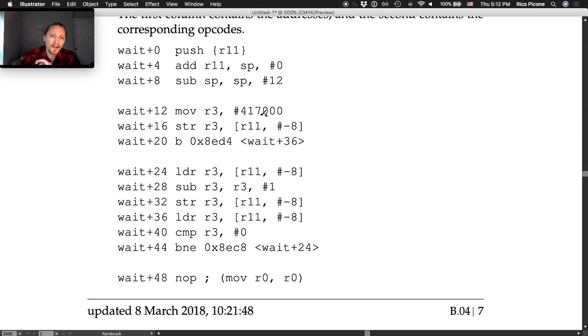And notice that our LDR commands, since we've got 417,000 of the LDR commands that get run twice in this because we've got it in the while loop, take up a big chunk of it. I think it's like 50%. I think LDR and move, and there's one other, I think compare.